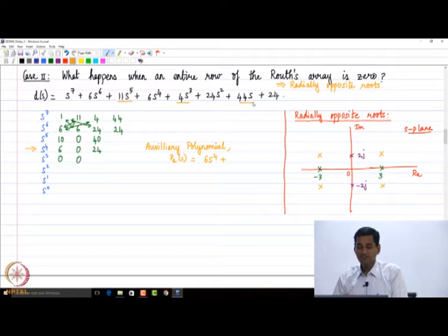So, in the auxiliary polynomial I start with 6, which corresponds to S power 4, and 0 S squared, so I just do not write anything, and then from S squared I just go to a constant term, S power 0 is constant, right. So, the auxiliary polynomial becomes 6 S power 4 plus 24. Okay, that is the auxiliary polynomial. And once again, I am just only stating the process and the results, I am not proving anything here, right. So, these have been well established.